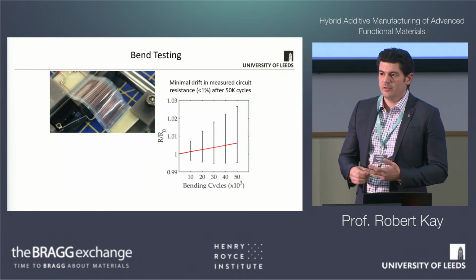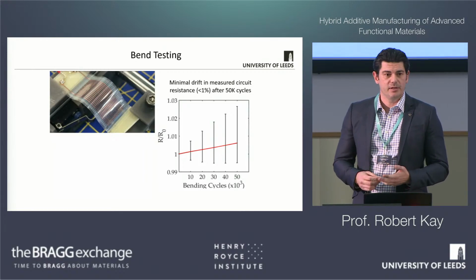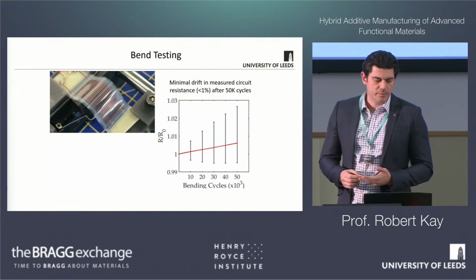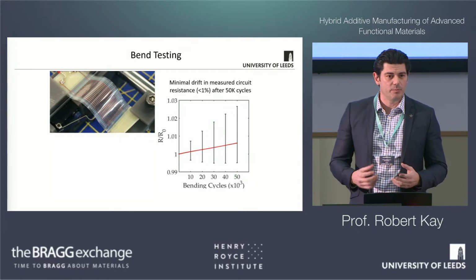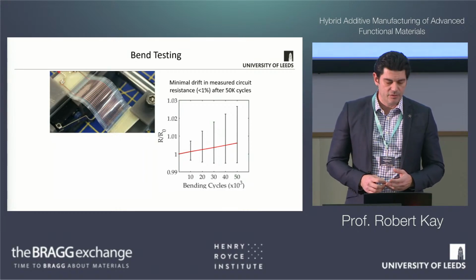So the first thing was, it was great every morning we'd come in the lab and see that it was still working. So it showed that reliability, the adhesion, but also we're really pleased to see that these parts had very minimal drift in resistance. It was only about 1% after 50,000 cycles.